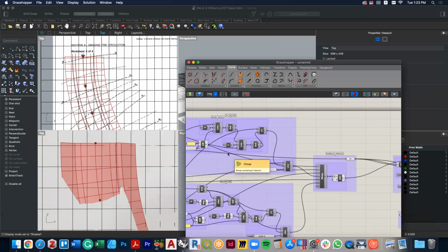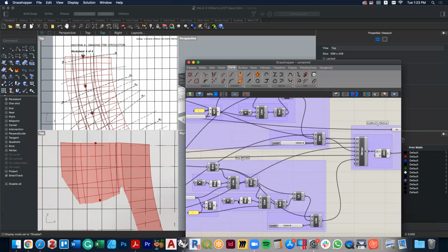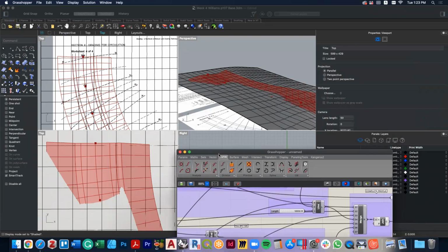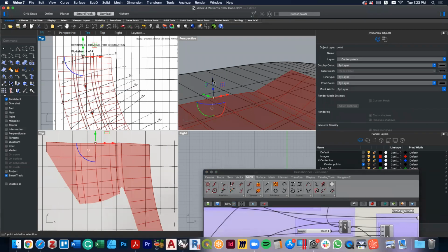So if we think about the fact that I have the cut batter, what I can actually do is continue that further out. That's 10 meters, right? So that tells you that if that's not disappearing in there, we're already too high out of the ground. And so if we go back into this space here, and I choose that point again, what happens if I go negative 500? You see how the fill batter is now reduced, so it's actually tapering off. Let's make it another negative 500.